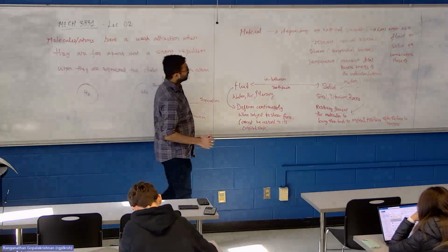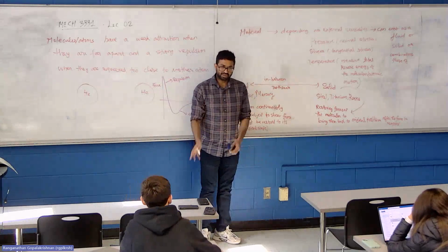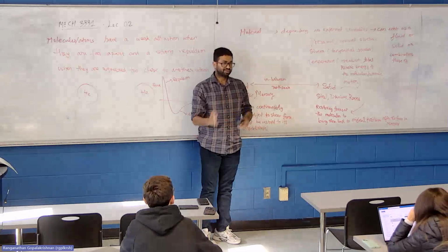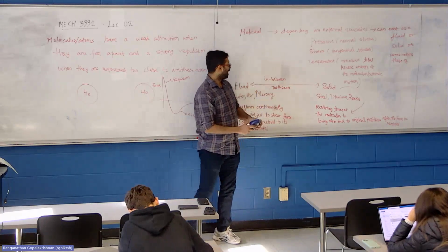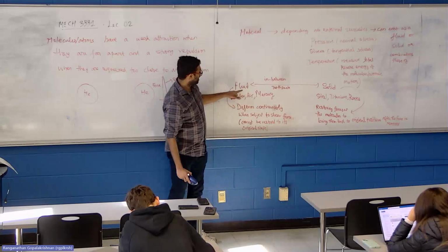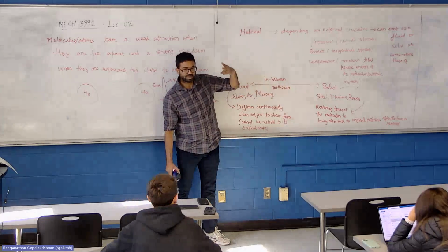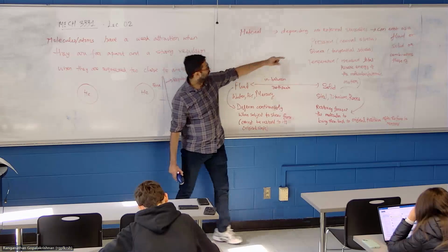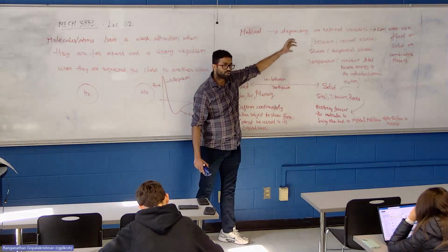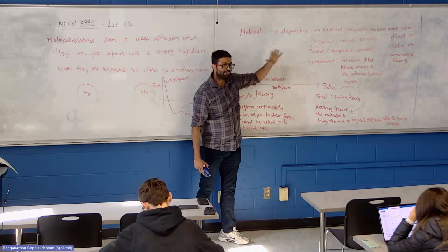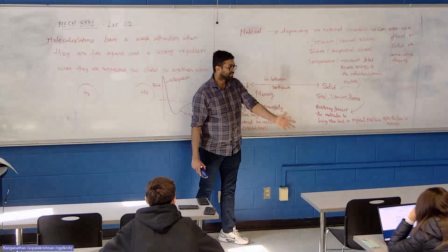What I want you to take away is that there is no such thing as a fluid or a solid in the strictest sense. Both fluid and solid are ideal adjectives or descriptors. Whether a given material will behave like a fluid or a solid or something in between depends on three things: pressure, temperature, and shear. How much you squeeze it, how much you shear it, how much you heat it. Make sense?